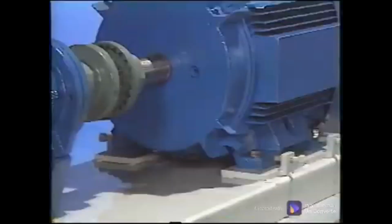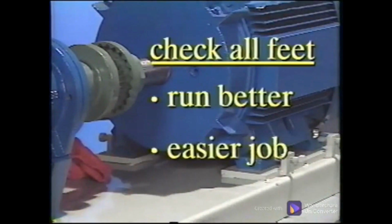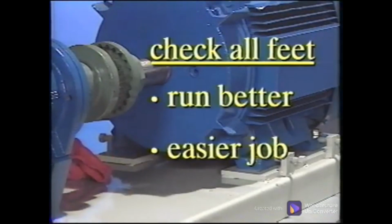When a soft foot is tightened down, it pulls on the machine and can warp or distort the machine casing, causing a bind on the rotor and preloading the bearings and seals, creating improper internal clearances and increased vibration. This soft foot condition decreases machinery life and causes even the most skilled craftsmen to chase their tail during the alignment process. Check all machine feet, correcting the soft foot, and the machine will run better, and you will have an easier job of aligning to tolerances.